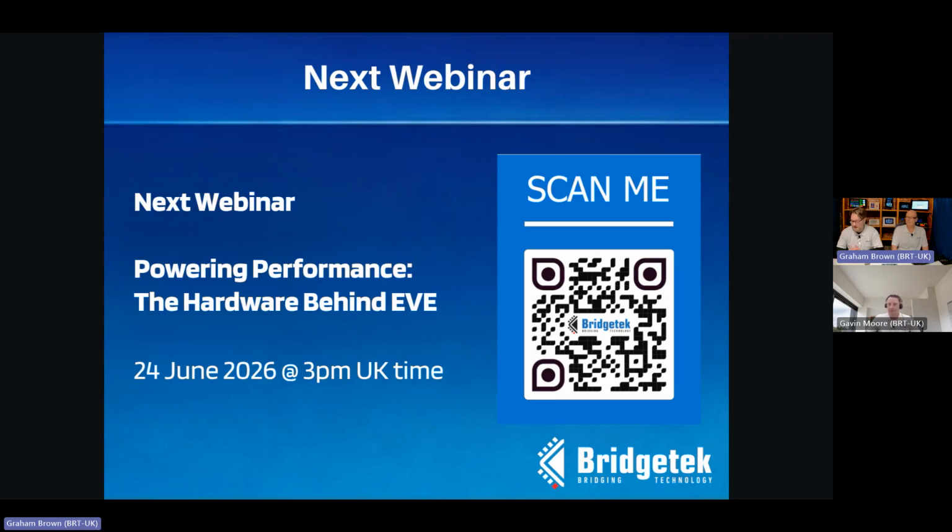Julian's asking another question. He says, the end result of compiling is SPI commands for the MCU to send to the Bridgetek chip, correct? The display program runs itself on the MCU. Yes, so the EVE series of graphics controllers take commands over the SPI interface, which you can find in the programmer's guide, the lower level commands. And essentially you are correct.